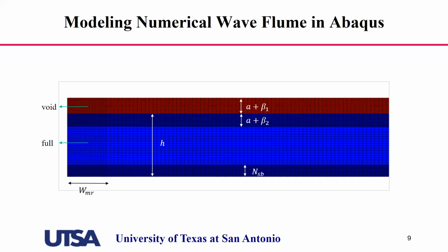The best way to handle this is to do a mesh sensitivity analysis. I have done it, but it's not finalized yet, and I didn't put it in the conference paper, so I didn't present it here. Are you talking about weeks with a supercomputer or with your desktop or laptop? On a desktop, it takes about 2 weeks. On a supercomputer, at our university we use 4 processors, and it takes around 1 week, actually less than that but close to that. It takes quite a bit of time. Yeah, impressive, but that's what it is.